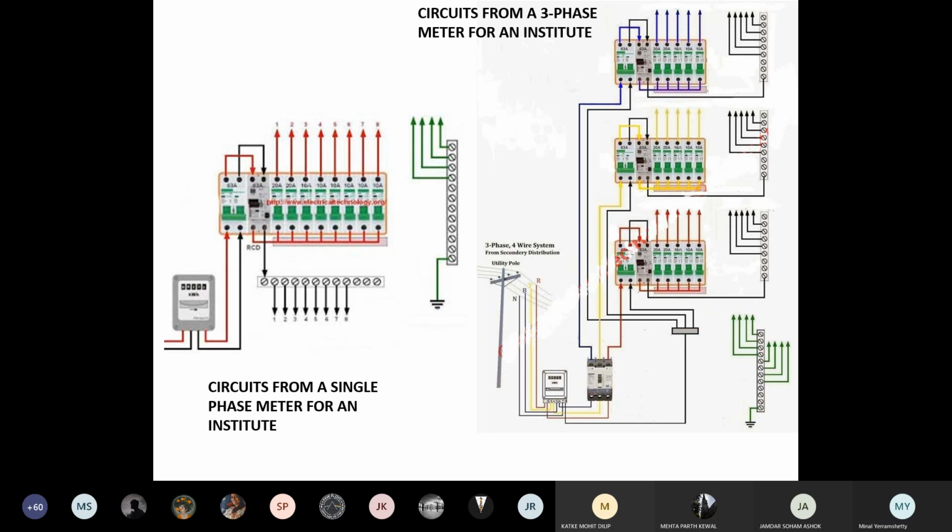If it is a G+4 building and I do this kind of wiring, it is terrible. So what I do is I do distribution in parts. I get bulk electricity at one level, and from there I do the distribution. And remember, one golden rule of electricity is every circuit has to be protected. Every circuit. The second golden rule of circuit protection: the shorter the length of the circuit, the easier to manage the heat. So I will try to shorten the circuits as much as possible.